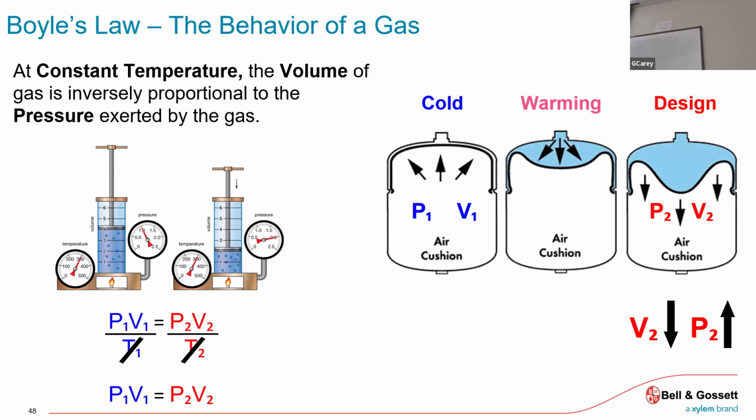Now you could say, hey, what's going on here? The key is the way the tank is connected to the system. I want to be able to valve it off, so I'm not reading system pressure. Then I want to have a purge valve, so any pressure here, I can get rid of it. And then if it's a simple little diaphragm like this, I might put something like a tire gauge.